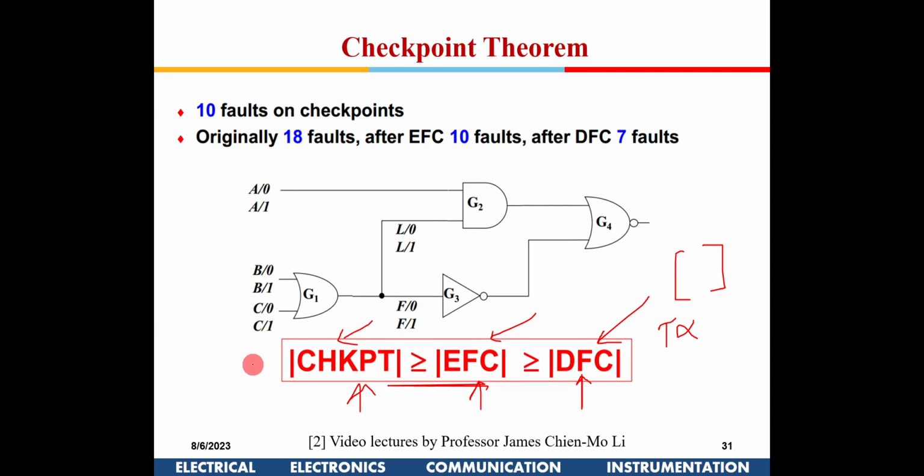You just run the netlist. From the netlist, you give all the faults at the primary inputs, and wherever there is branching in the netlist, you give again all the faults. Simple. It will take just a few minutes for even a very big circuit with a few thousand transistors, or maybe one odd hour. This will give me the entire fault list. This is the simplest algorithm.